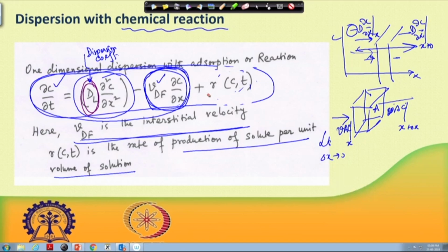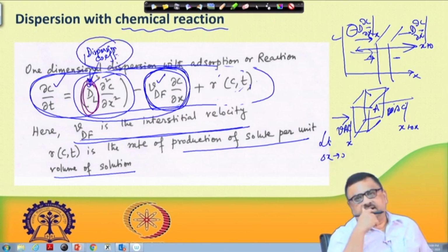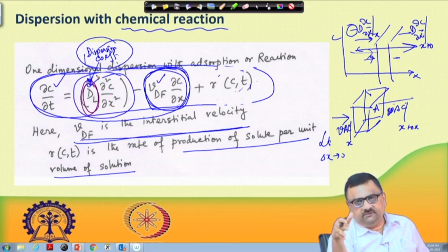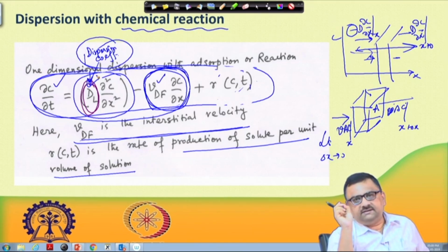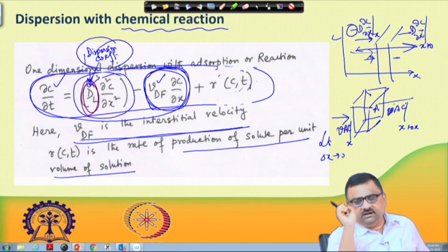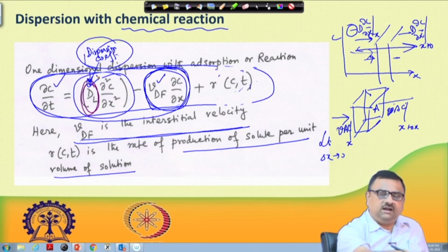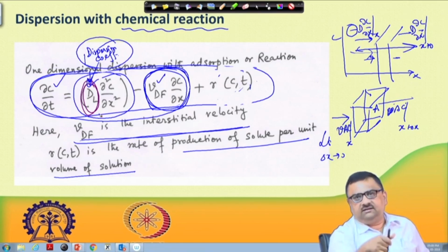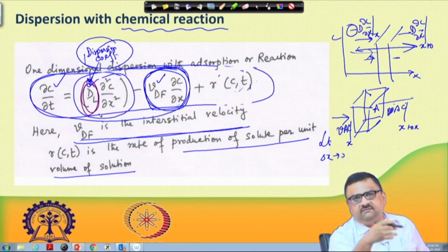And now this dispersion coefficient that we talked about, you can define. If you have some idea of the radius of the pore, you can go by r square v square by 48 d, or simply r square v square by 48 d. One needs to have the understanding of what is r and what is the true diffusion, the bulk diffusion coefficient. So, those informations are required, or if you have some experimental data, one can fit for that same porous medium and find out the dispersion coefficient by fitting the data points through the equations that we discussed so far.